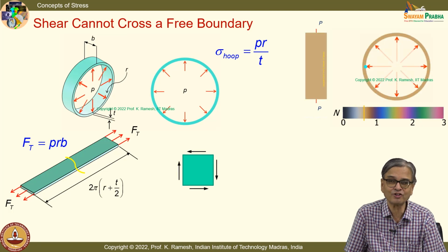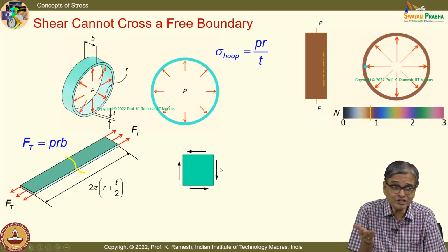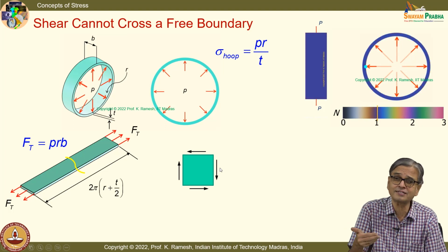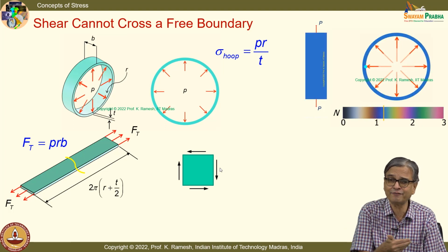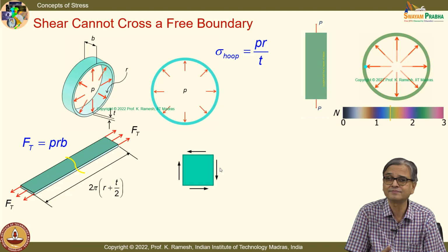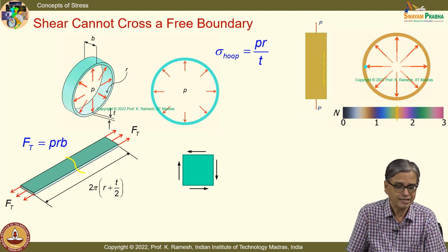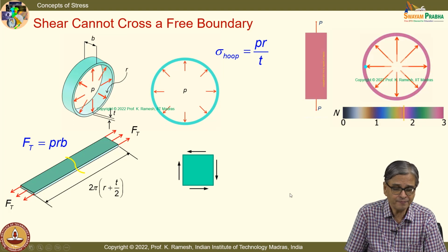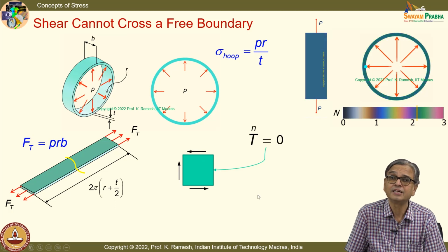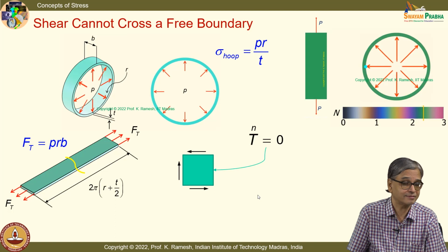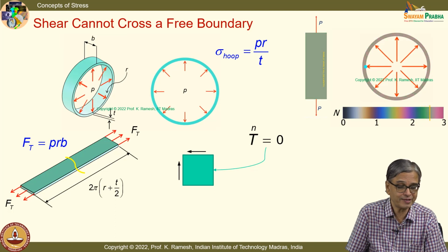Okay, can there be shear on this? There is no shear. It's only axial force that is applied there. Okay, radial force is applied on this surface. Fine. But I can still have a normal stress, and that is what you calculated. You have this as a free boundary.